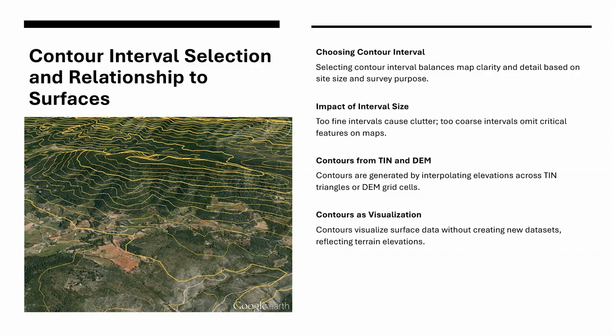Too fine of an interval and the map becomes unreadable spaghetti. Too coarse and important features begin to disappear. Selecting the proper interval for your project is an act of judgment, reflecting both the scale of the map and the purpose of the survey.